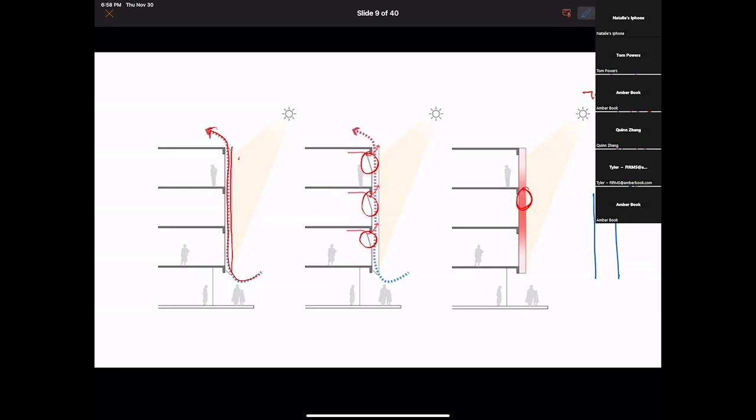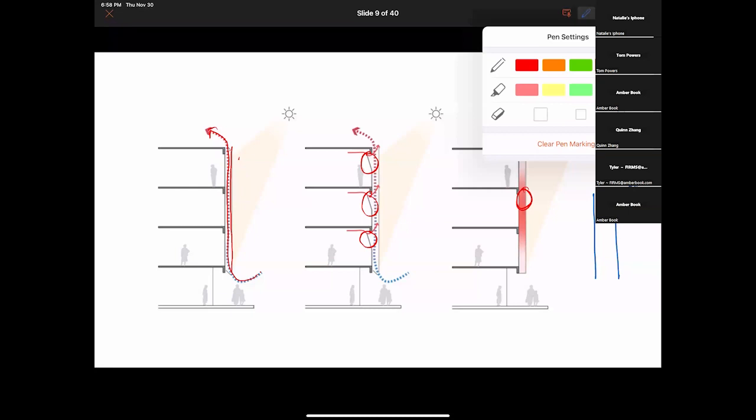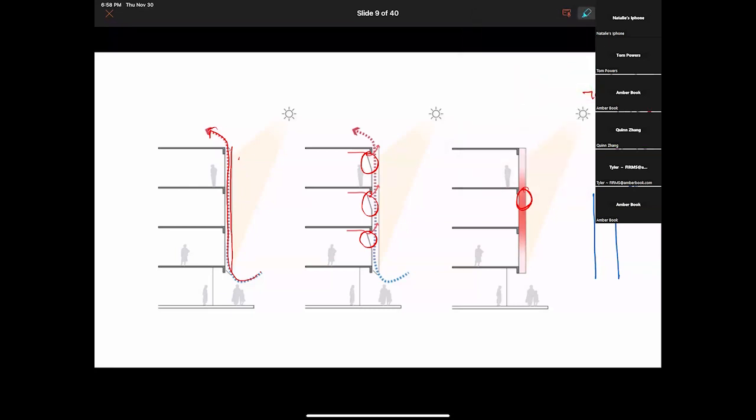And the double skin facade was just kind of like it happened, and then they stopped doing it? No, they still do it, but it's not a loop. They're trying to cool their building. What I just drew is moving heat from inside to outside or from outside to inside, depending on the season, and we don't want to move heat from outside to inside. Completely separately, what the double skin facade is doing is saying there's heat that would have otherwise gone in, and we can exhaust it. We can capture it before it goes inside the building and send it out. So that's convection, but not a convective loop.